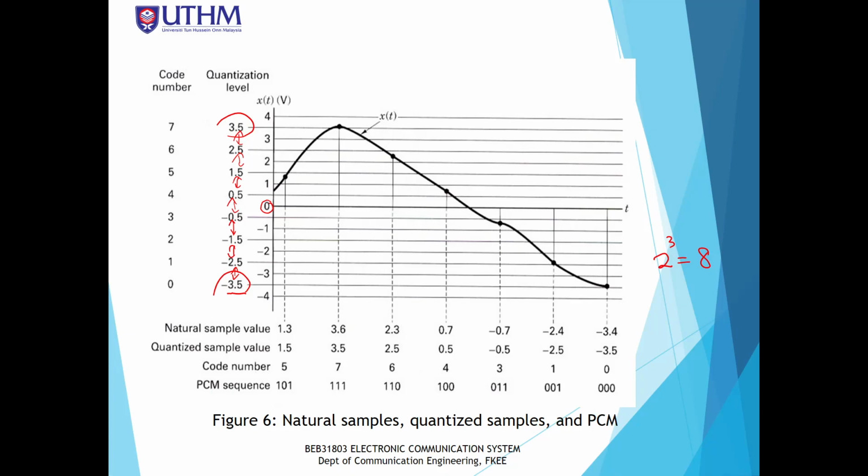The quantized levels are divided equally, positive and negative side, so it is like a folded binary, which is centered at the x-axis. In this example you can see that the resolution is the same, 1 volt, or the step size, the distance between each level.